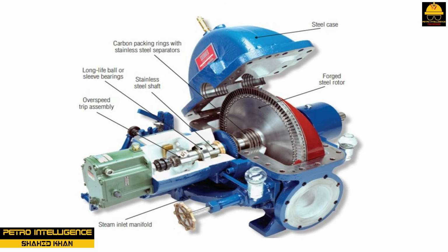Steam turbines are typically classified as condensing, non-condensing, reaction, or impulse. In condensing turbines, exhaust steam flows to surface condensers. Condensing turbines operate at vacuum pressure. In non-condensing turbines, exhaust steam is utilized in low-pressure steam applications. In reaction turbines, steam is discharged from a nozzle mounted on the rotor. Movement is a reactive response to the release of steam from an internal source.